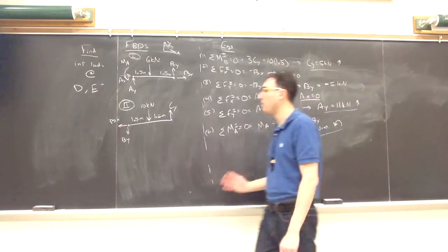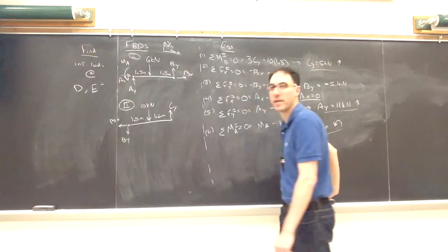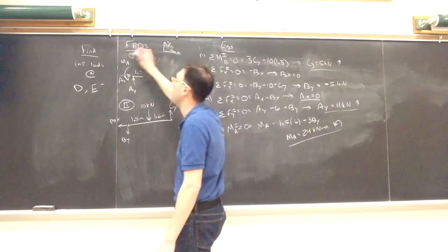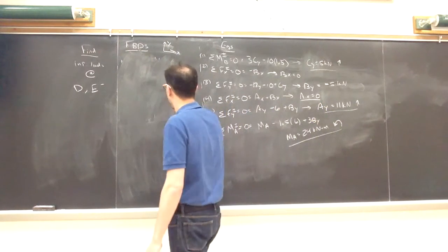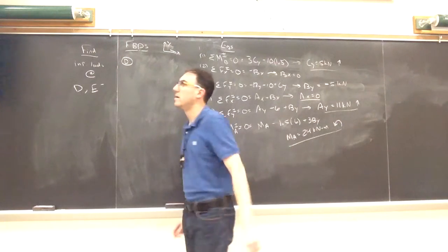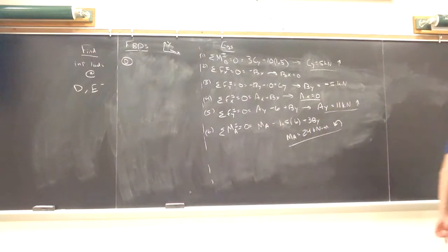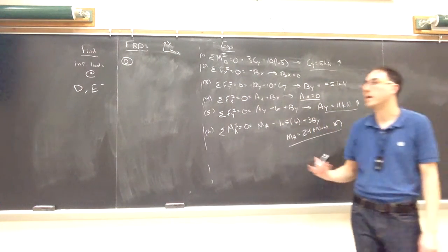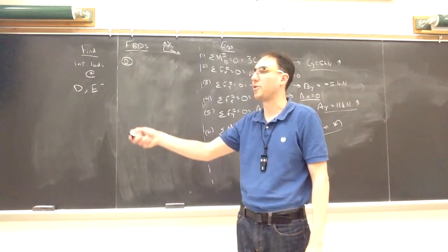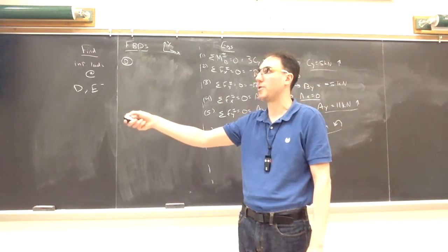Right, so now the new, more interesting piece, actually attacking what the problem is asking for, the internal loads at D and at E. So I'll start at D, make some more room here, and draw its picture first. Like we saw on Wednesday, since it doesn't say otherwise, I'm always going to be making a perpendicular cut through that point. So if the beam is horizontal, I'm going to make a purely vertical cut through point D.